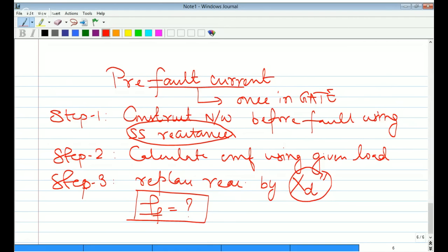Okay. So what it has done is: resultant MMF is equal to field MMF plus armature reaction MMF. Because when it is saying the MMF required, that is basically the field current, or the MMF required to overcome armature reaction. Okay. So that is corresponding to FAR. Once I have field MMF and armature reaction MMF, we can calculate the resultant MMF.